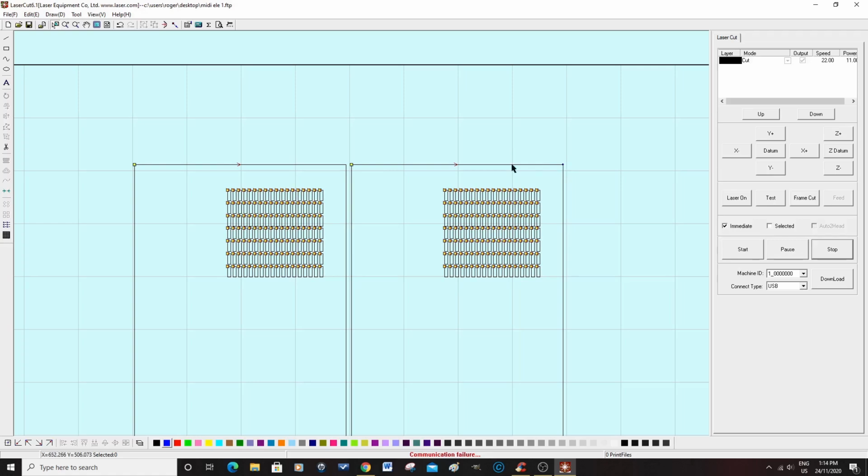Then third, we need to cut this one out, then come back and cut this one out. Because otherwise, if you didn't tell the laser in which order to cut, well, it could come in and cut this, try to cut this out first, then cut these, and it just doesn't work. Because this piece of material could move, and it wouldn't cut in the right area.